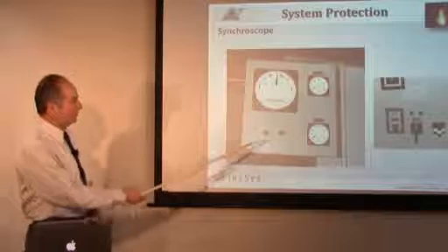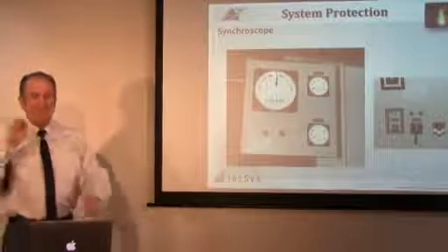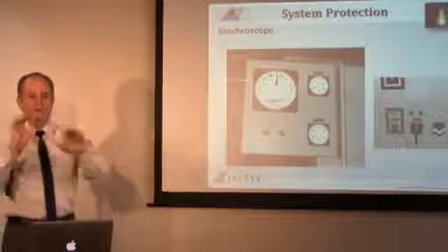In the old days, we used to do it with lights. You used to have lights for the system and the generator, and when you got them close, blinking together, we could close. A little bit crude, but that's the way it was. Nowadays, we can really lock into a nice clean sync, and when that generator kicks in, you hardly even know it. The transient on the voltage is minimized.